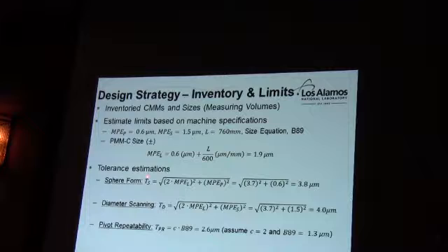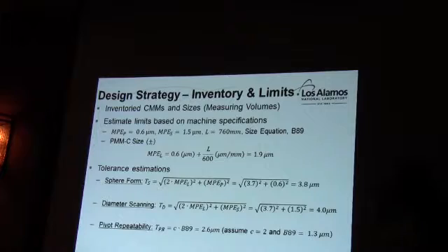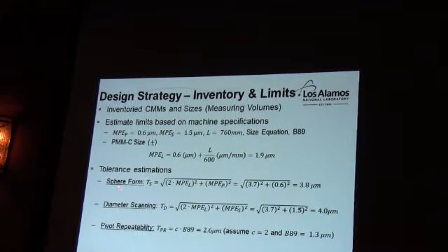So basically, now we looked at tolerance estimation. I'm going to try to explain a little bit of what we're doing here. When you're using a machine checking gauge, it generates, or simulates, a large sphere like I mentioned. The CMM is tactically taking points at 3 different levels at 45 degrees. I'll get into that in the next slide. But basically we're trying to estimate our tolerances.